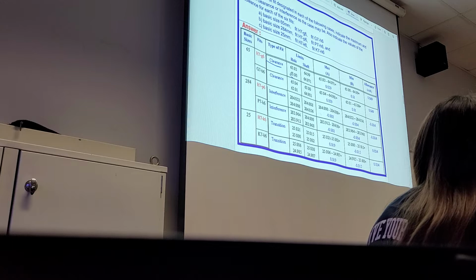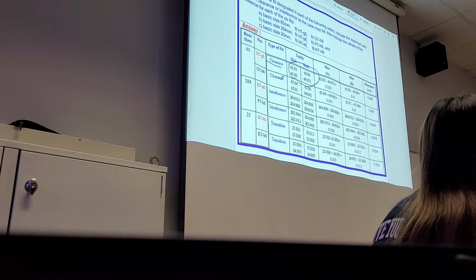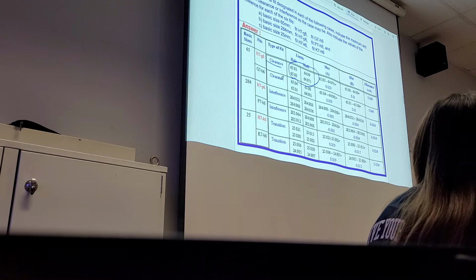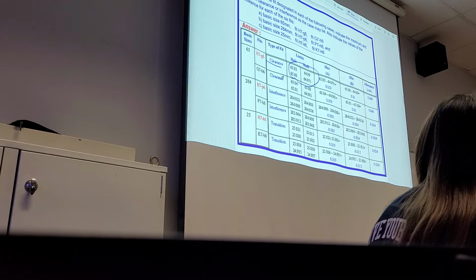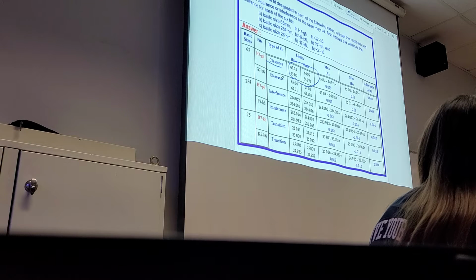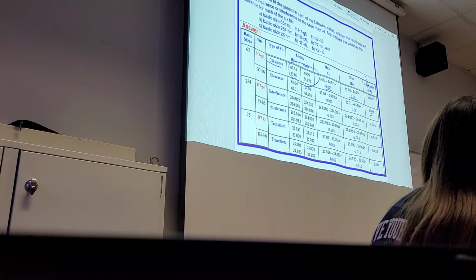So where do we get these values? From the table again. Based on the nominal size, basic size 65, and the specification H7 G6, you get the upper limit and lower limit for each part. And from here, you can find out the maximum size, maximum clearance, and minimum clearance. The allowance you can just leave, you don't have to bother so much.